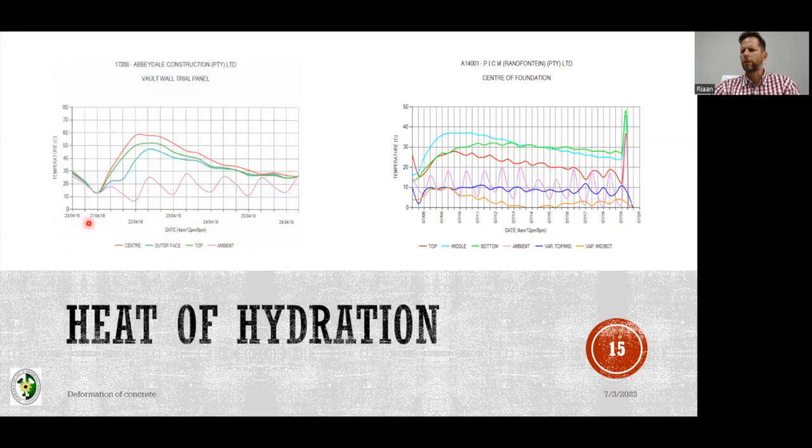It might have been on the 20th sometime. The exact date of placement becomes quite interesting if you look at the temperatures. I have a picture at some point where the temperature of the concrete initially was above 30 degrees centigrade. So we then learned to allow the trucks time to also just dissipate the heat.